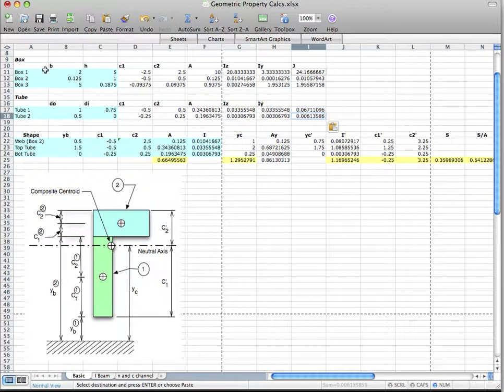composite sections, right? These are the primary base cross-sectional areas, the fundamental geometric shapes that you use. And then we're going to add them together down in this portion to get the total properties, okay? So again, the big things we're going to get are the location of the centroid.